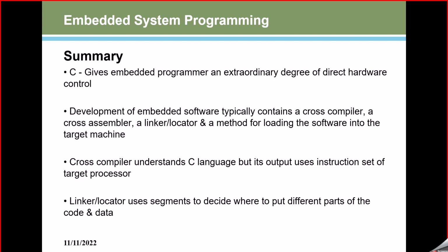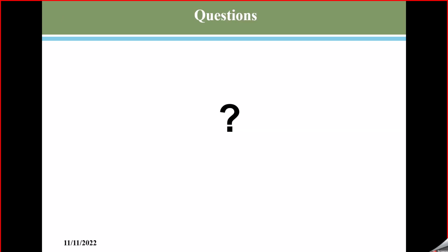And as a summary of the embedded programming concept, we should learn C language concepts so that we can carry the same things forward into the embedded system. We have different compilation stages in embedded C and in C also. Both are the same, but there is a little difference. Cross compilers are used to compile the code for the microcontroller, for example the Keil compiler. Do you know the linker and relocator? Generally, it will link all the library functions together, and the linker will assign the physical base address in memory to start running. Clear?